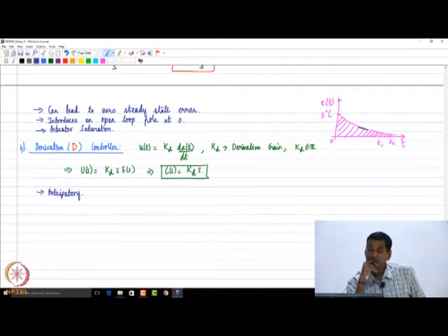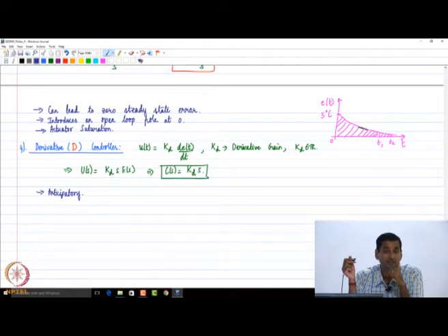So, that is one perspective, what he told. But more importantly, is there any other concern that we may have from derivative control? We will look at it from a response characteristics perspective later, but we are now trying to get an intuitive understanding. It will make it unstable. Oh, that once again, maybe if you have sharp changes in the error, you may exceed the actuator's limits. Okay, agree.